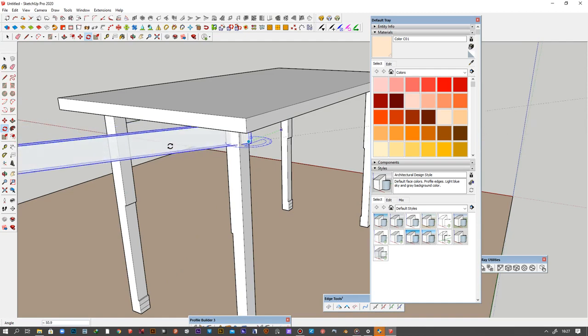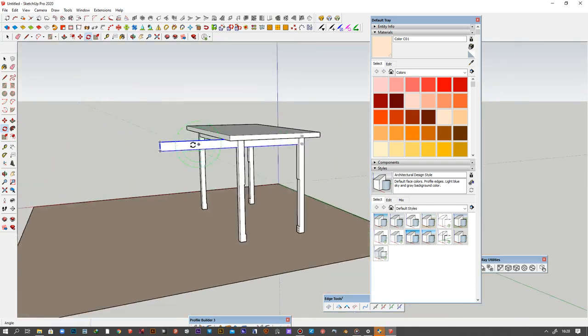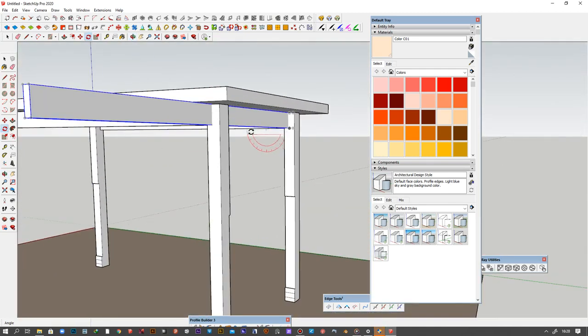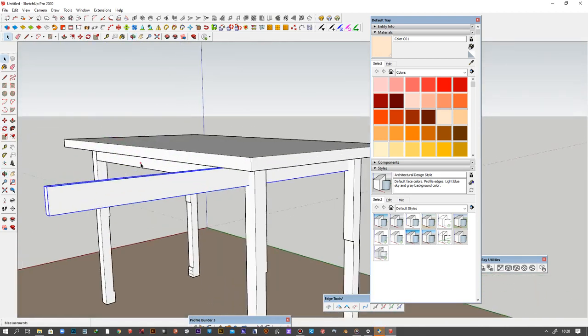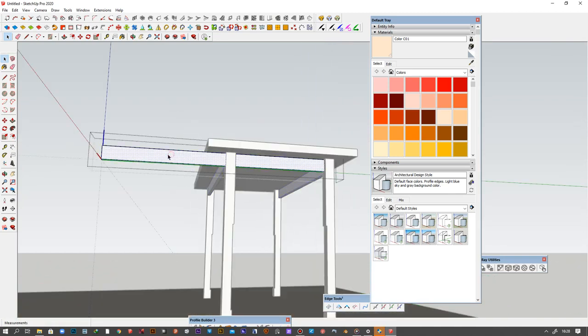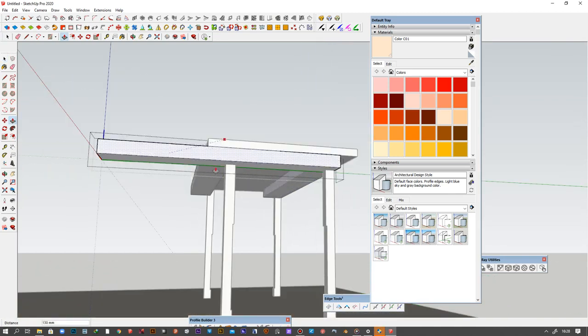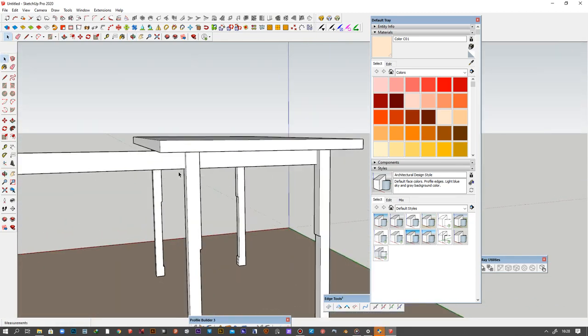Also, while rotating, you can hit the control key to create a copy, as you can see, and you're able to achieve the same effect. Now we have this and this as components, so editing this edits all the other components, yet we have a smaller distance right here.